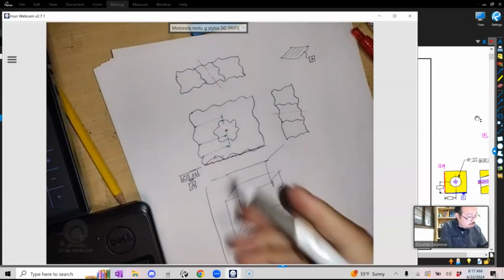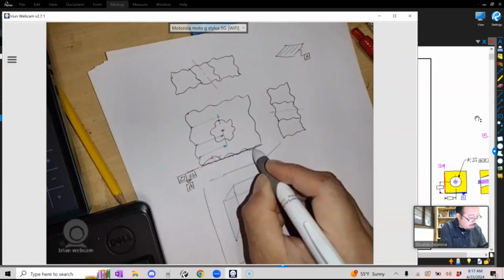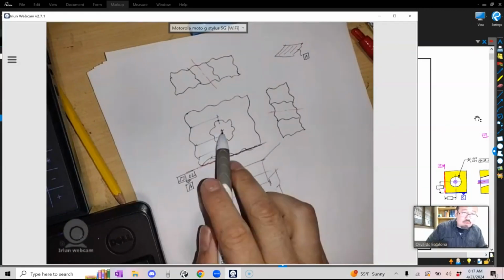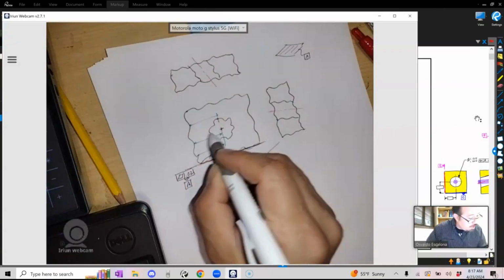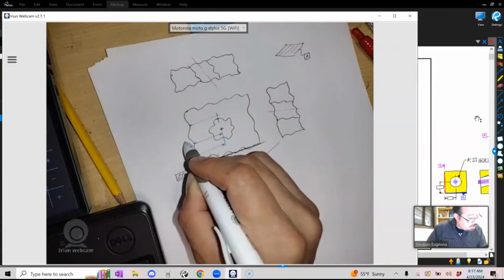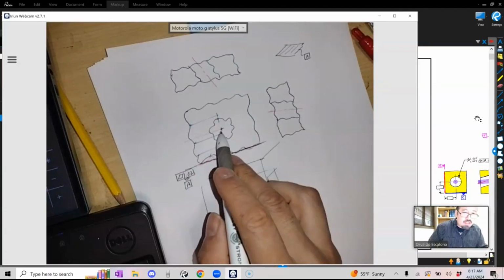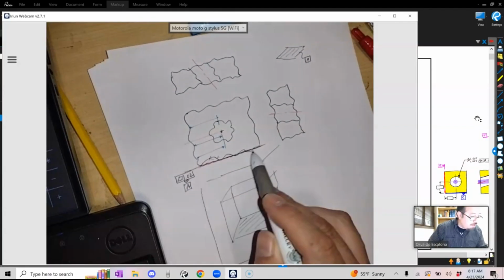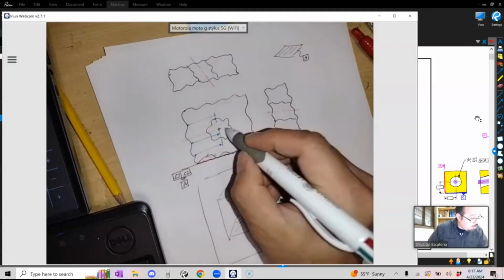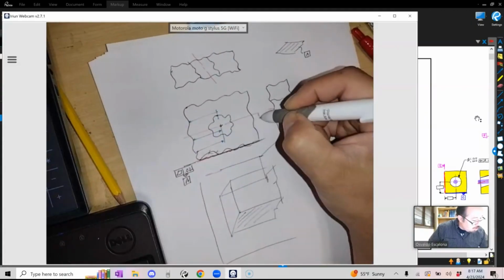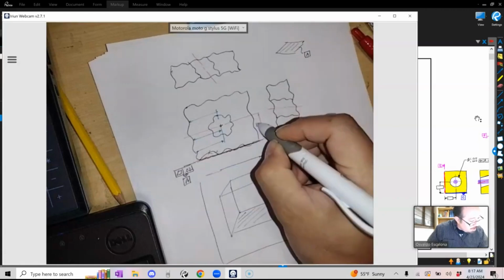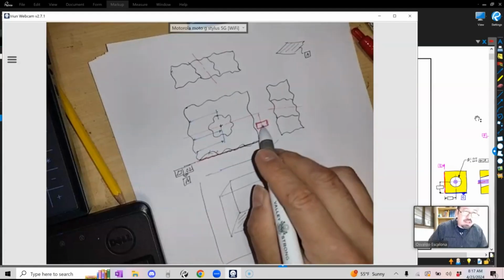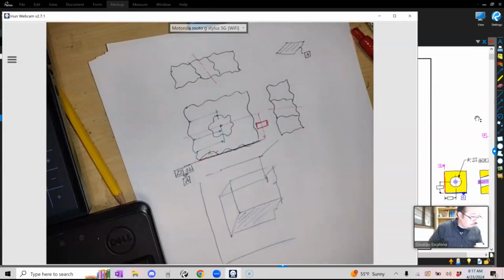Remember, when we're talking about datum, we are talking about theoretically perfect. Okay, theoretically perfect. This true bullseye here, I am going to be controlling the location of the bullseye, not the size. So, for example, now that I have established the reference frame, I can go straight to theoretically perfect. And I'm going to put a box, and I'll explain in just a second what this box is about. I'm going to put a box in my location, my true position.